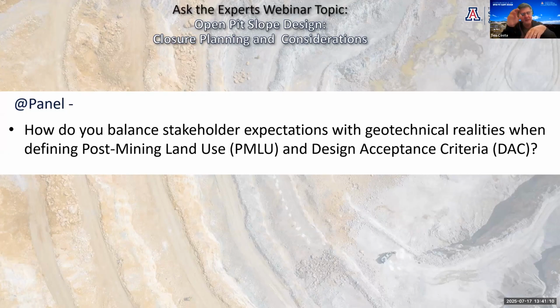The FOS, the POF could still be a guide, but what defines the quality and the longevity of the structure should be the performance, based on monitoring and visual evaluations. We don't lose slope stability analysis and give FOS or POF. We're still using this, but not as a main guide for the quality and the effectiveness of the slope or dam, this type of thing.